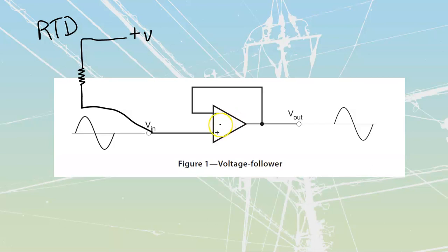Now inside of here, there are paths all the way through to my negative or to my ground. What I'm going to do right now is leave those paths open for the time being. We're going to refer to them in a second. But we're going to refer to this RTD. These RTDs are designed to carry tiny, tiny amounts of amperage, milliamps, or in some cases, microamps. That's it for the maximum that we can pull through, because if we pull more current through them, they do have what we refer to as a PTC, a positive temperature coefficient, which means that as they heat up, so as heat goes up, then the resistance would go up.